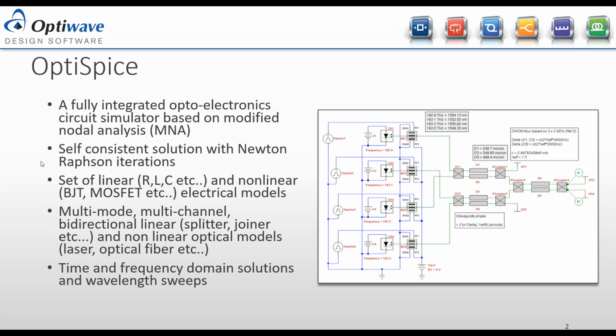But if we wanted to simulate the carrier in full, we would have to take very small time steps, because a signal generated by a laser will have a frequency in the terahertz range, whereas we're looking at electrical bandwidth, which is going to be in the gigahertz range. So the way we're avoiding this problem is by simulating just the envelope of the carrier and the phase. By keeping the phase in the envelope, we can still do interference effects, for example.